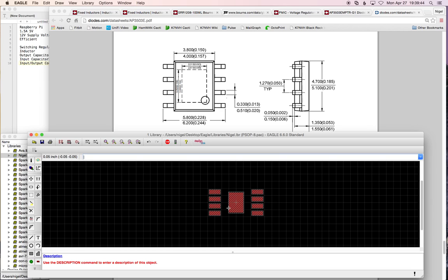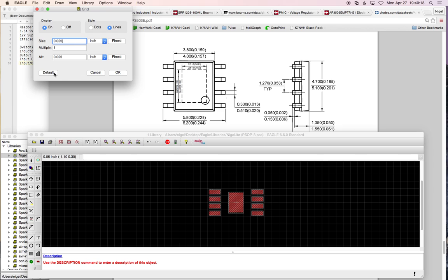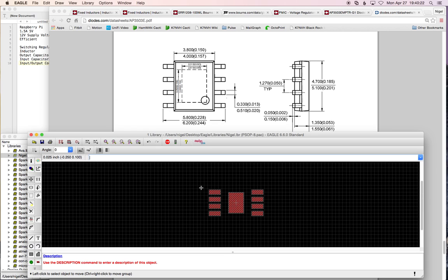And so what we're going to do is bring in the pads here, these edges of the pad, closer to our center pad. And then we'll still expect that our total width will be wider than what they give on the dimensions here, but that's okay because we're making our pads longer on purpose. We just want to make sure that we get our pads in far enough that we get the pins on there nicely. And so probably what I'll actually do here, make this easy, is set my grid to a bit smaller, specifically half as small. And so now that we've got our vertical positioning on these pads set, and I could have done the grid thing too as well here, I just didn't. We can grab the group and do the whole set like that, and grab the group and do the whole set like that.